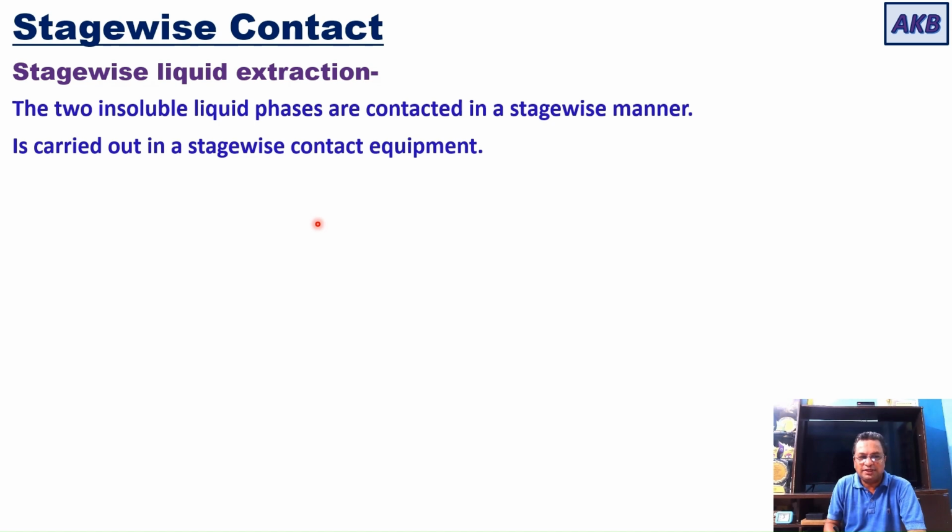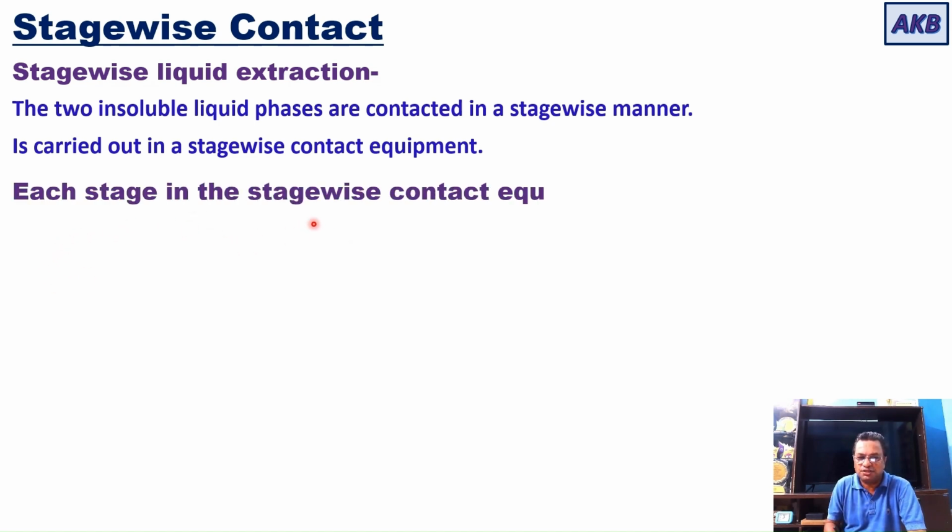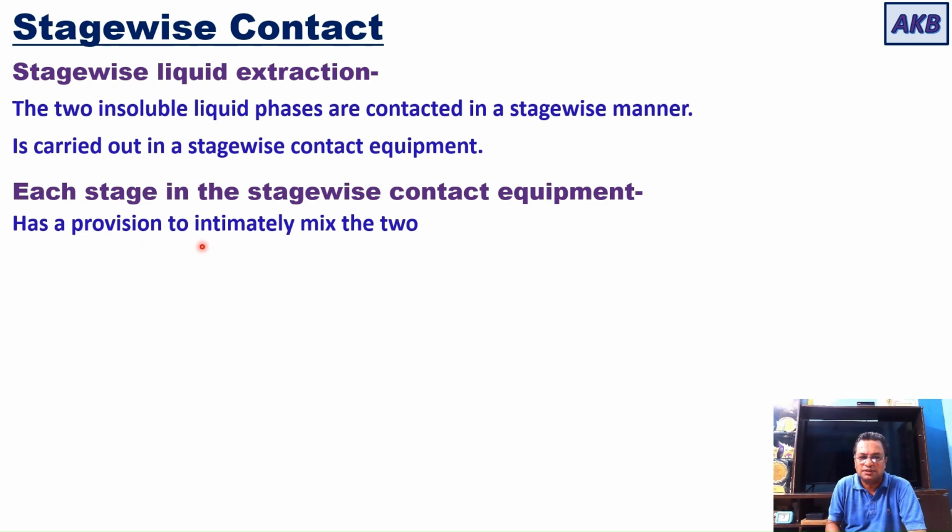Especially in the case of liquid extraction, each stage in the stage-wise contact equipment should have a provision to intimately mix the two insoluble liquid phases, feed and solvent.